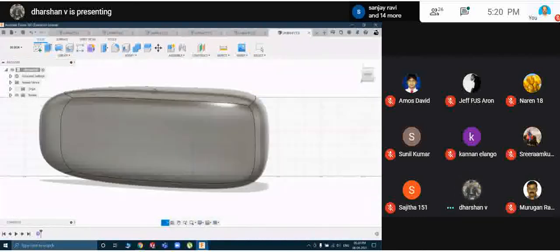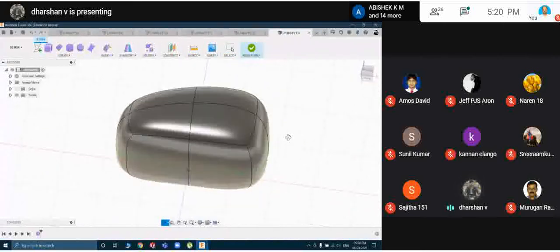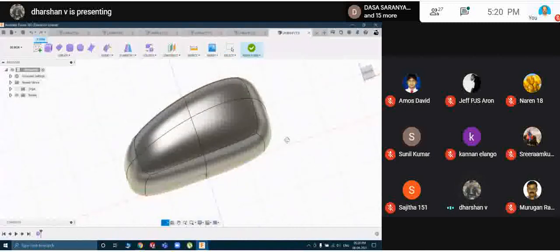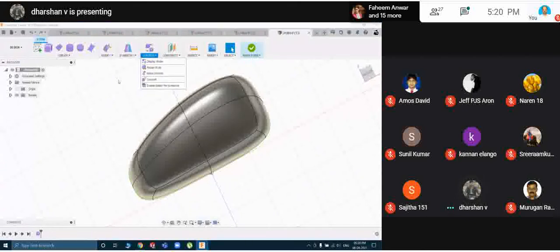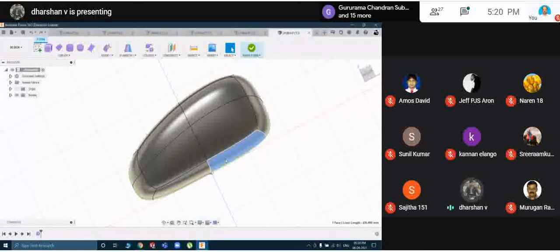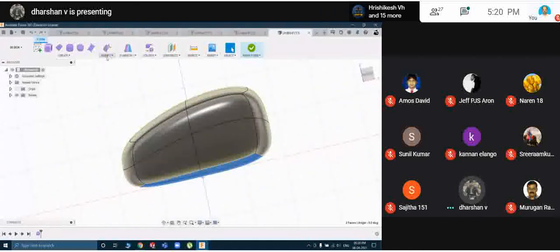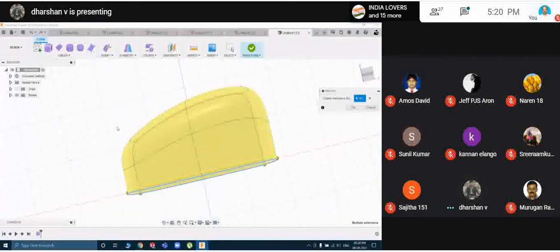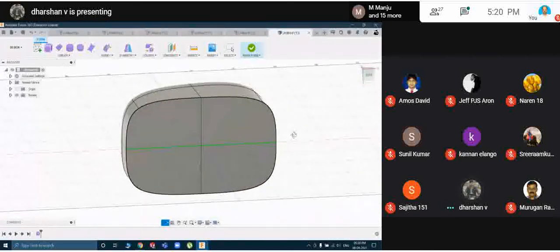Is it interesting? Now I can just do a mouse also. Look here. Imagine it's a computer mouse. The bottom has to be straight, flat, right? In that case, I will select this space and this space, go to modify, and there is something called crease. Can you see crease? If I crease it, what will happen? See, it has become flatter.